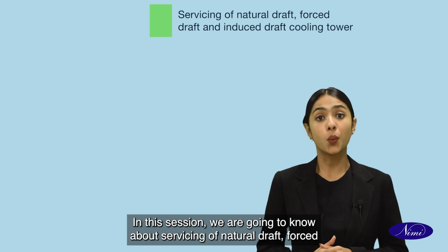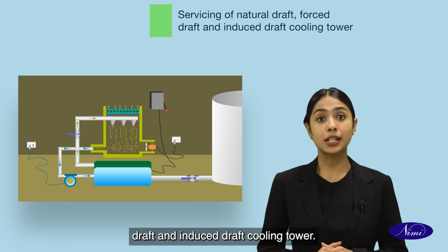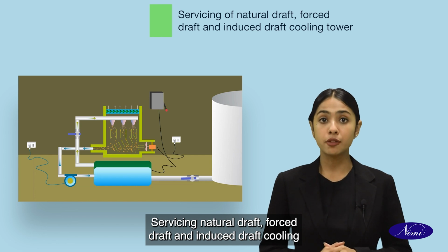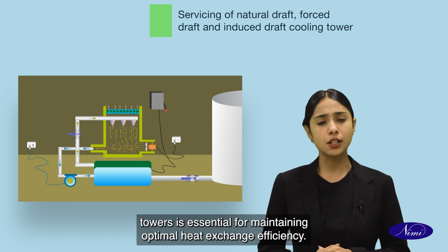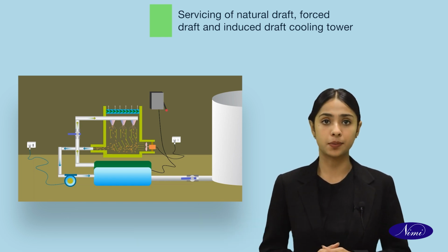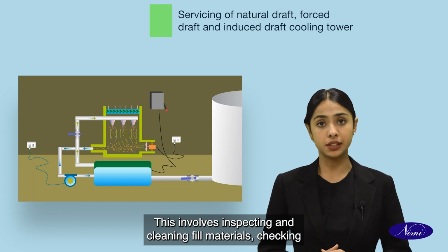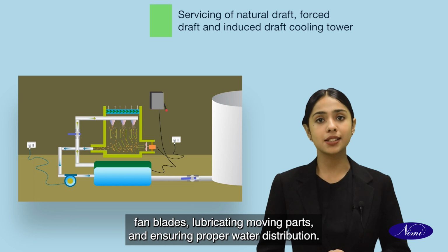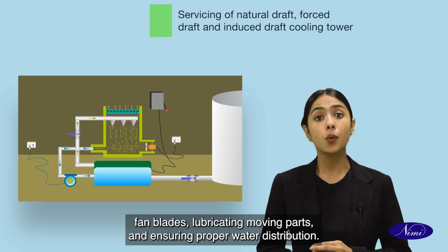In this session, we are going to know about servicing of natural draft, forced draft and induced draft cooling tower. Servicing natural draft, forced draft and induced draft cooling towers is essential for maintaining optimal heat exchange efficiency. This involves inspecting and cleaning fill materials, checking fan blades, lubricating moving parts, and ensuring proper water distribution.